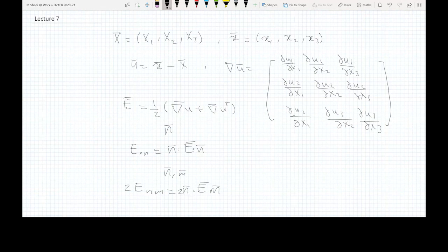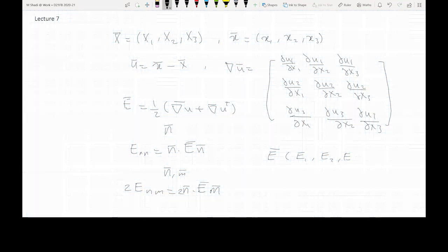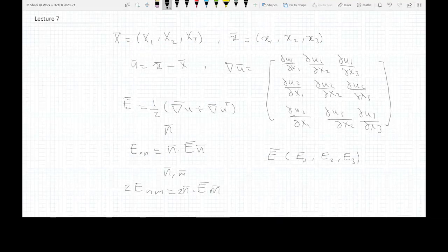And obviously we have the strain tensor, the E tensor. You can find the principal strains, E1, E2, and E3. So this is the maximum change in the length in any specific direction. We identify the directions by solving the eigenvalue problem, and then we get the eigen directions. So the eigenvalues are basically the maximum change in length in the direction of the eigenvector.